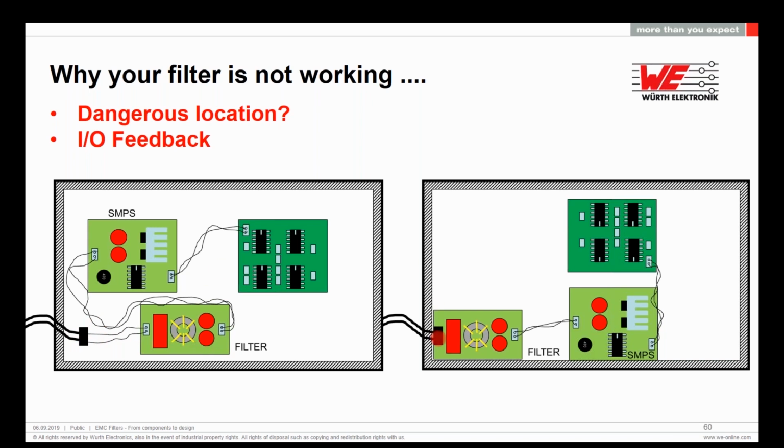So try to place the filter as close as possible to the input, and always put the input and the output of the filter in series and not crossing, or in parallel, or close to each other.